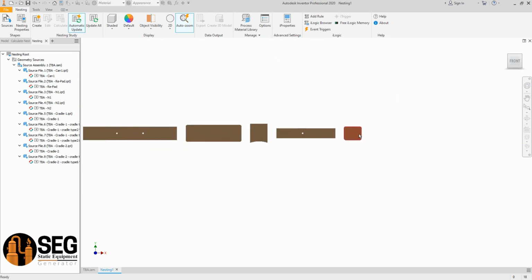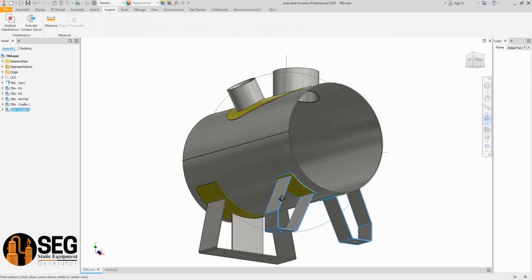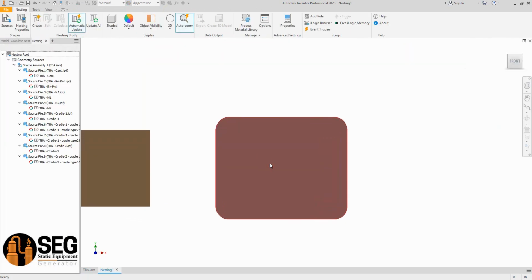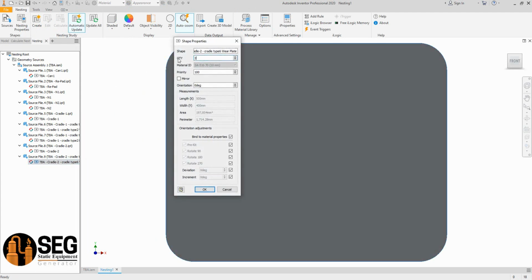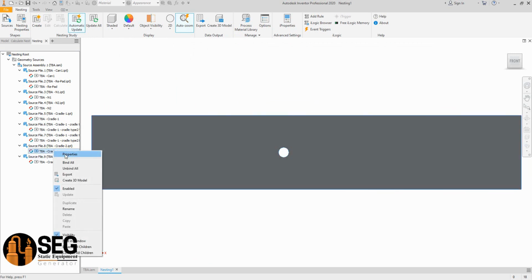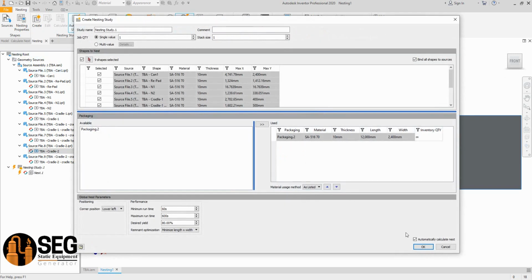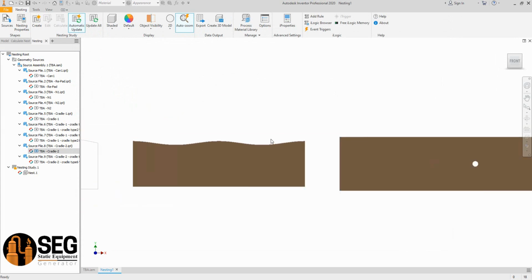One more thing here for the rebed for that cradle and the development of this plate. We will change the number of items to be 2 pieces, and for that one, let's define it to be 2 pieces. Now let's create the nesting study. Select the suitable options for the arrangement and create your study.